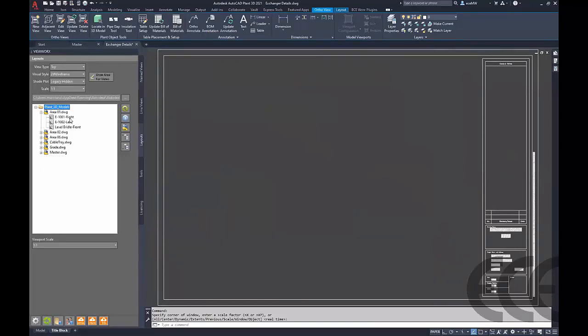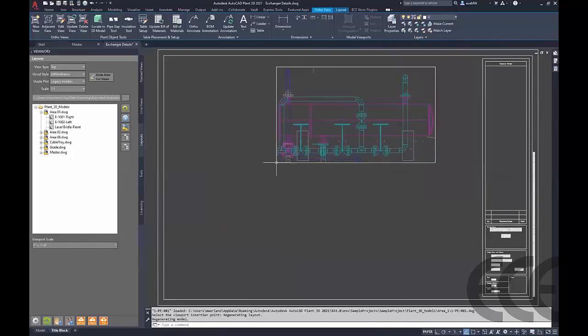But when we're working with details, you might need a little bit more control over what you're inserting into every drawing. So by just creating a new drawing through the project, we have our template in place. And now we can just go through and select which views we want to insert. We choose the scale that goes along with that, and then use the insert option. And as we select them and insert them, it's going to go through and, again, bring in all of our XREFs. So you don't have to worry about finding which XREF belongs to which view. It brings them in, sets the scale, and then locks it. So very quick, very easy way to get all these detailed drawings in place.